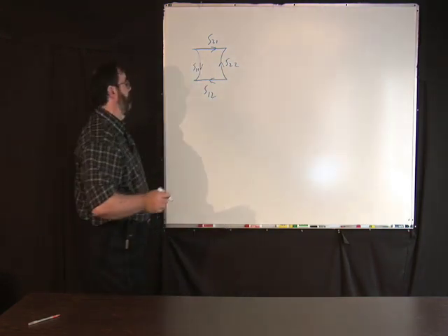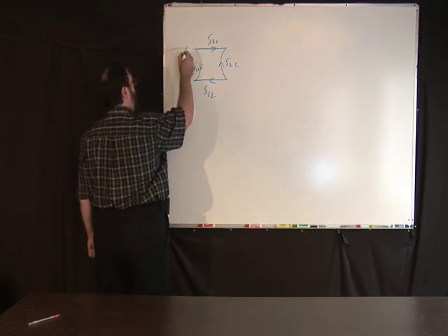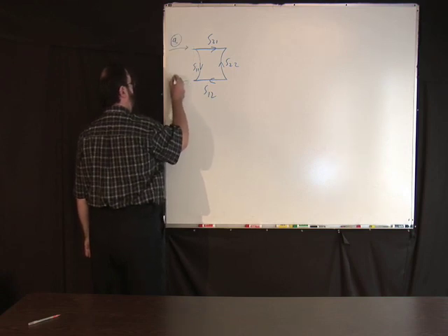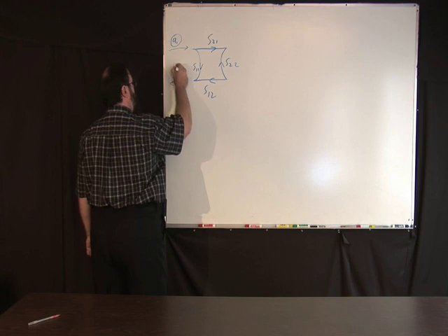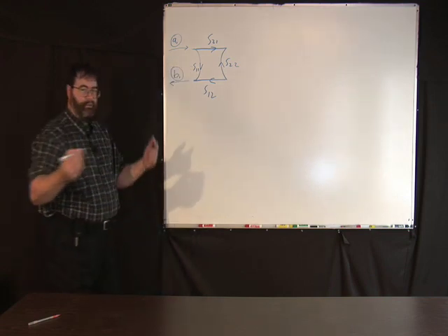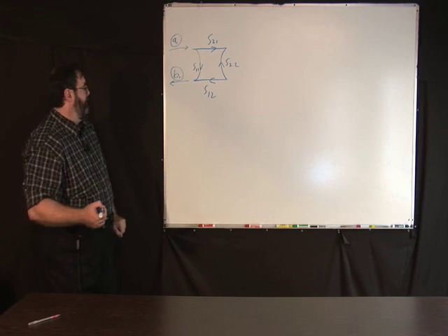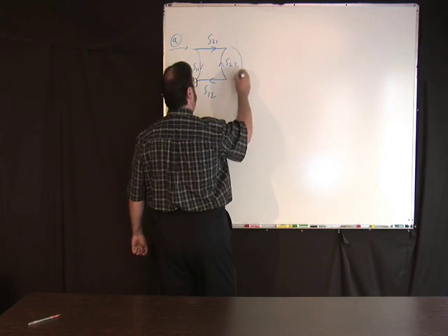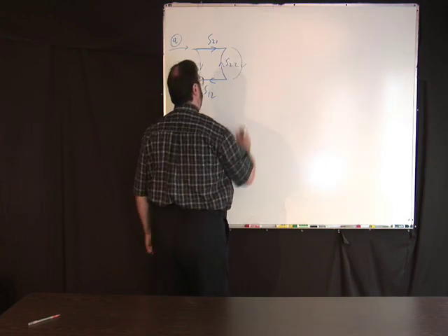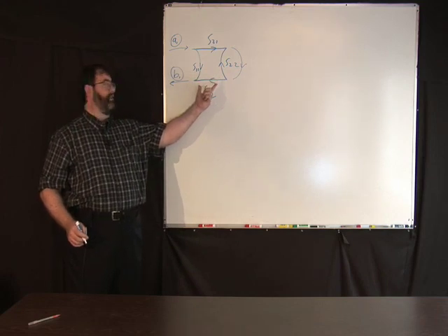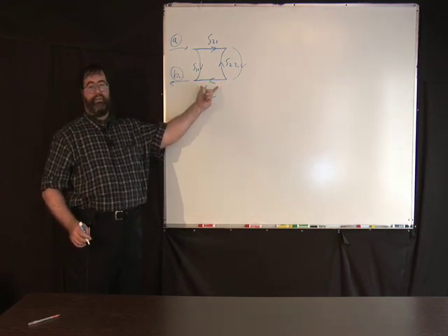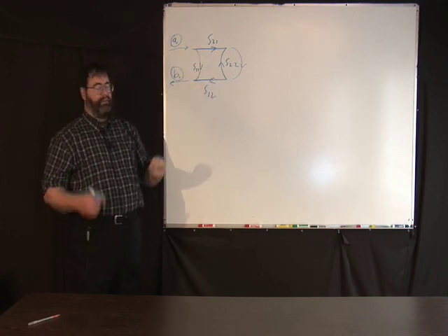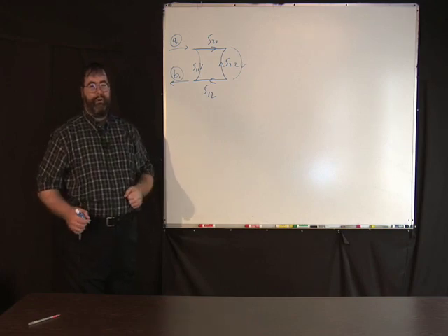Okay, so we put in some signal here, A1, and we measure some signal here, B1, and we talked about measuring the amplitude and phase difference. Then you put an unknown load out here. I emphasize this two-port represents the reflectometer, so it's a series of errors. If it was perfect, this would be 1, that would be 1, this would be 0, and that would be 0, and then your reflectometer would read perfectly.